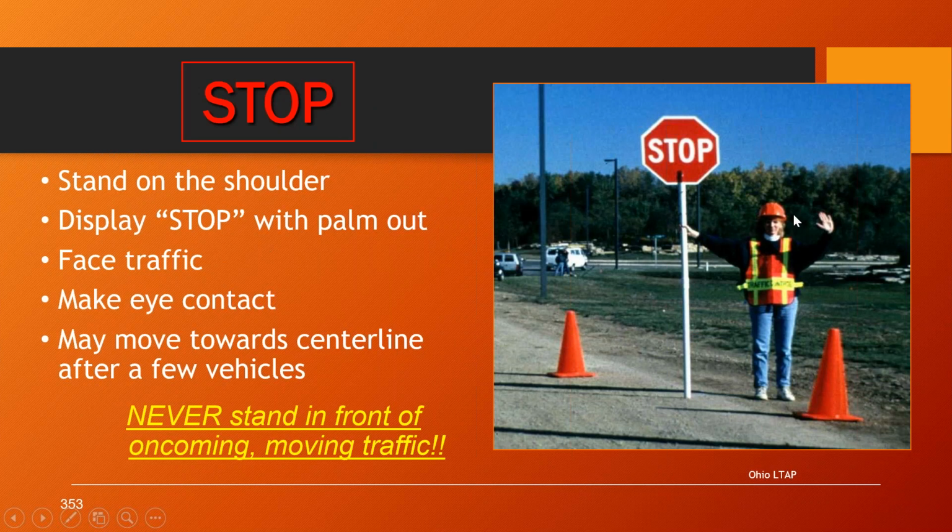A little bit more, another picture here showing how to stop traffic, standing on the shoulder, displaying the stop with palm out, facing traffic, making eye contact. And then after you have a couple of vehicles stopped, then and only then can you move out to the center line so that approaching vehicles can see you in case you're blocked by that traffic.